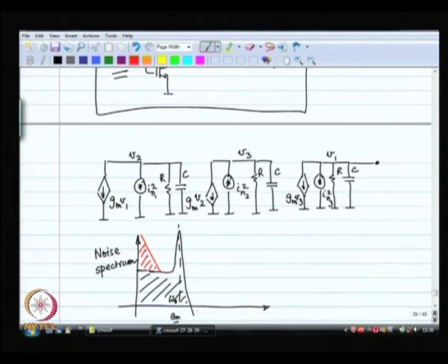So, all the noise over here is phase noise, it cannot possibly be amplitude noise, the amplitude is a square wave. So, all the noise that you are seeing is really expressed at the output as phase noise or jitter, uncertainty in the period of the oscillation.